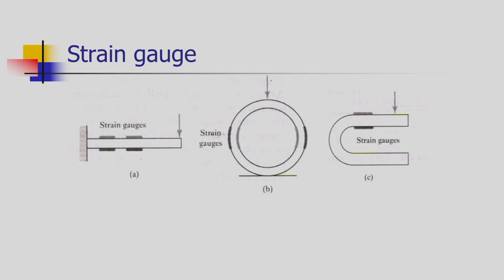Now, on your screen you can see how vibrations are measured. Suppose we are applying a repetitive load at the cantilever beam, the load being applied intermittently. The strain gauges pasted on the top surface experience tension due to the tension in the fibers of the top surface, while the fibers on the bottom surface of the cantilever experience compression.